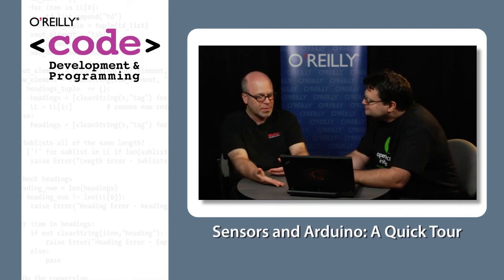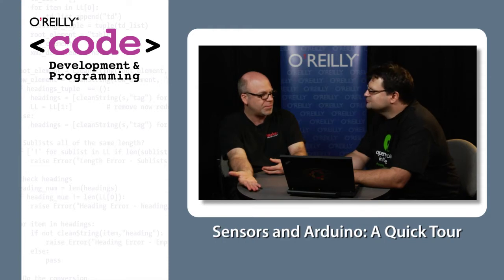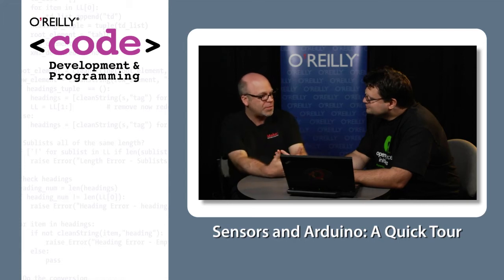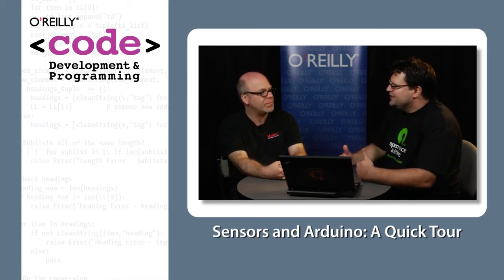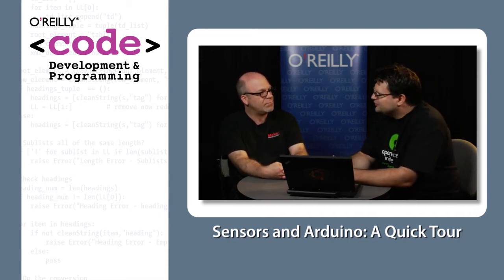If you're programming against something that's strictly linear, like most potentiometers, most knobs you turn, then 0 is 0 volts, and 1023 is 5 volts, or vice versa, depending on how you hooked it up. And something in between, you just scale linearly. Others may have a dead zone where they don't trip for the first 40 values, let's say, and then the linear behavior starts. So there is a little bit of adjustment here.